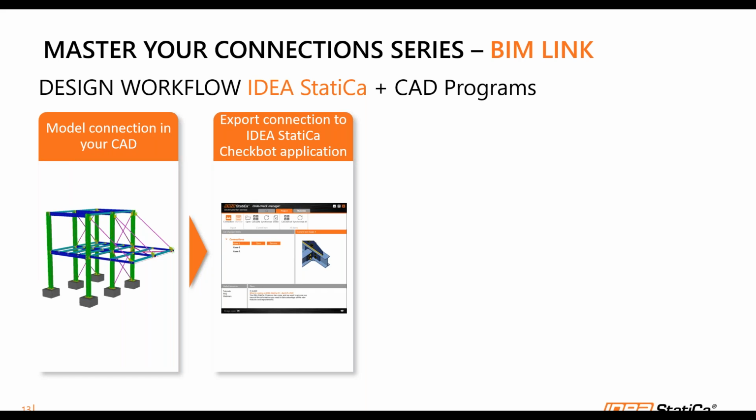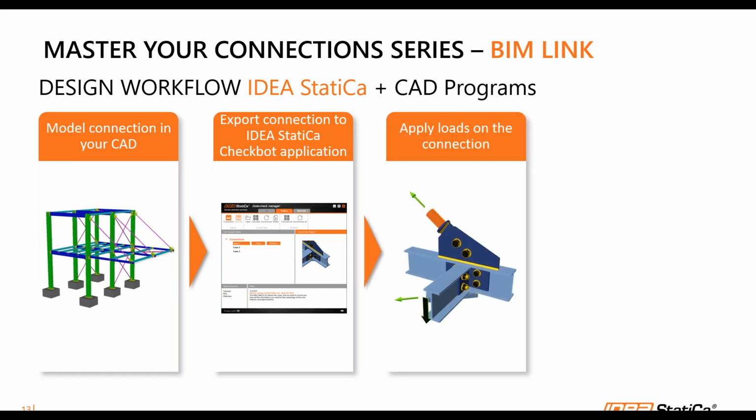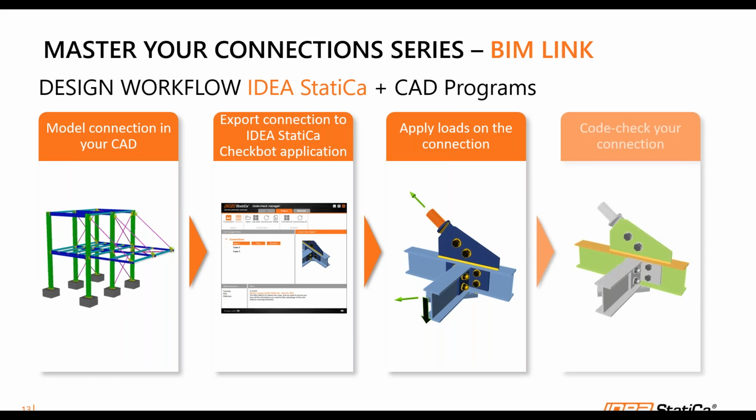But since it's a CAD program, the loadings are actually not present, so there are no loads being captured. Bolts and welds are automatically captured in this Checkbot application, so you do not have to worry about anything. All you have to do is apply loads to the connection, and once you apply loads, you can just run and code check your connection, and that's the basic workflow using your CAD program.